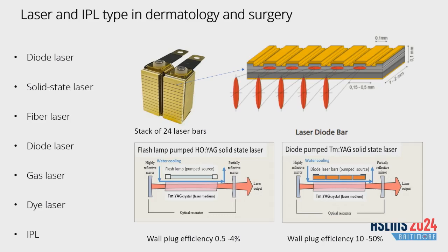solid state laser. This solid state laser includes an active rod, which is about the size of my finger, with an active medium including ions which generate light, doping the crystal. And this rod we place between two mirrors, which create our lasing. So to make the lasing effect, we use a flash lamp with a very, very broad spectrum to pump the rod, and photons travel between the two mirrors many, many times and generate laser energy.